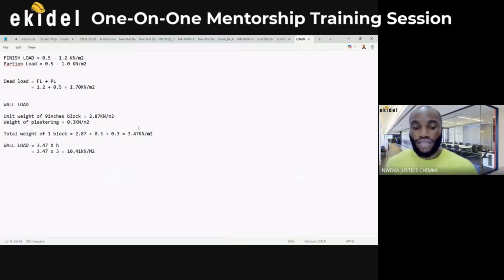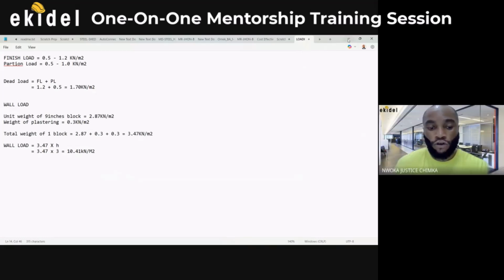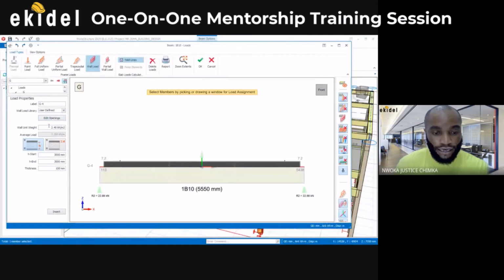So you say it is 2.5. Okay, that's fine. So you now come and add it here. Wall unit weight 2.5. And then you can see they are asking you what is the height. Now this height here is not basically the height of the story. It's the height where the block will occupy.